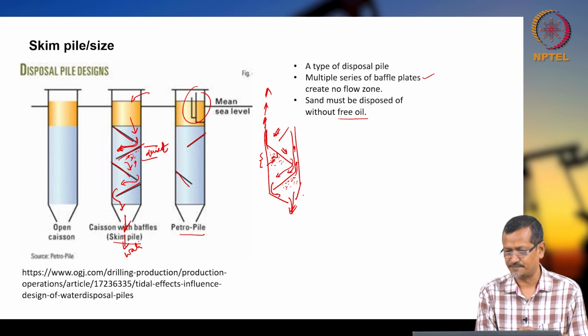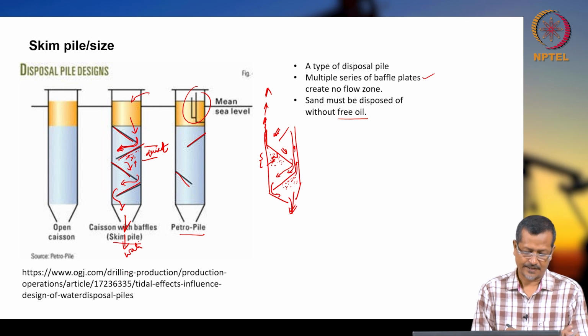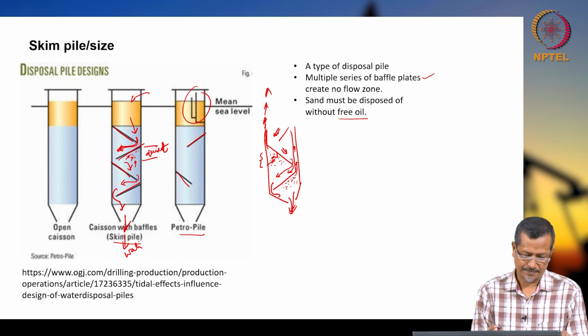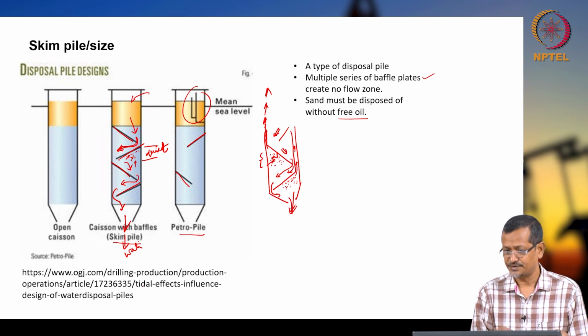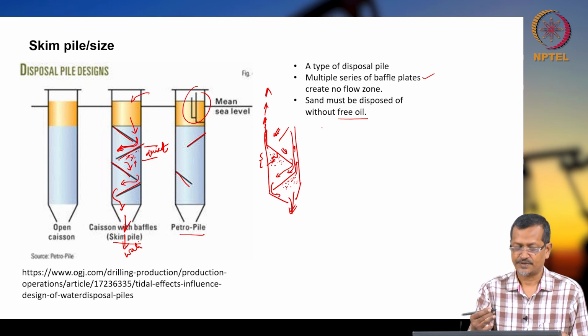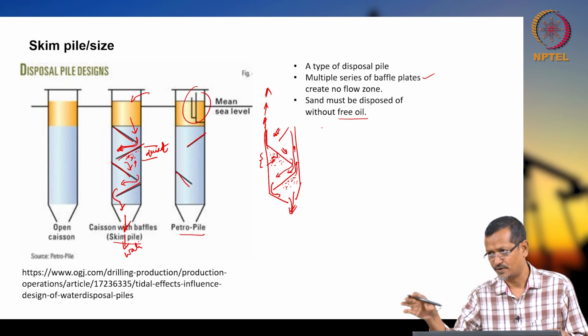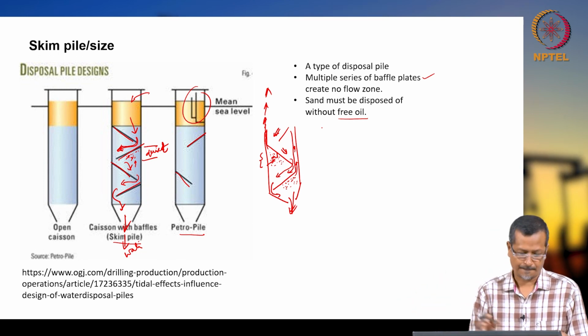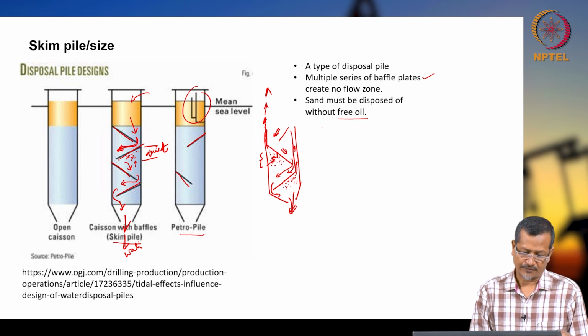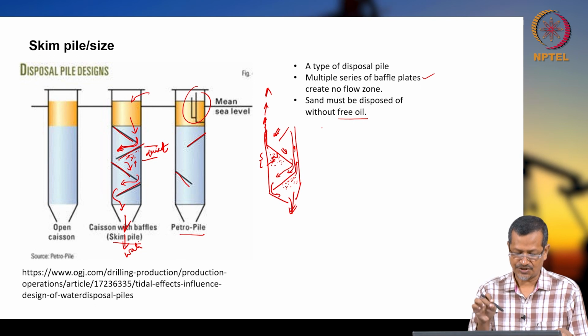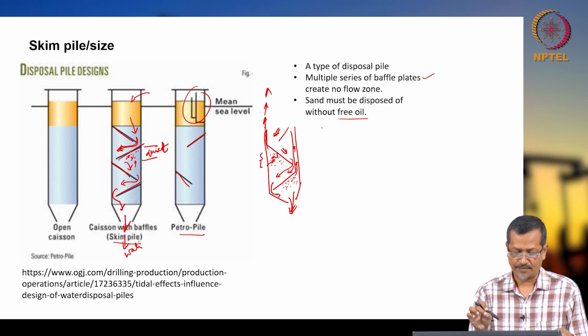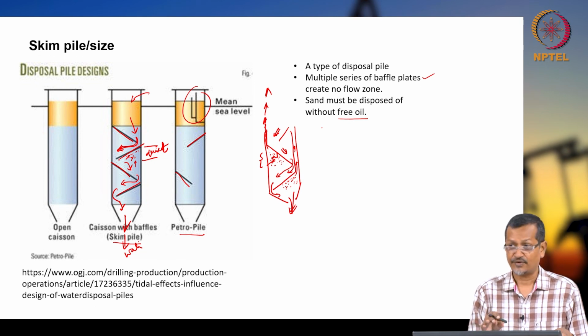This is the offshore system. So, the disposal pile, a large diameter open-ended pipe, concentrates all platform discharge into one location. So, all platform water will be collected into one location. Then it provides a conduit protected from wave action, so that the discharge can be placed deep enough to prevent sheens from occurring during upset conditions. It also provides an alarm or shutdown point in the event of failure.